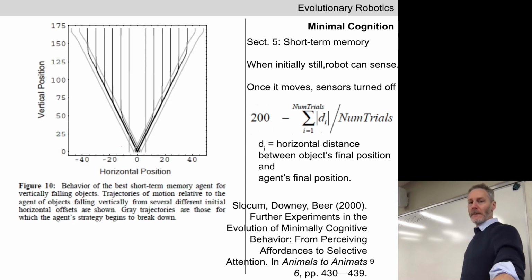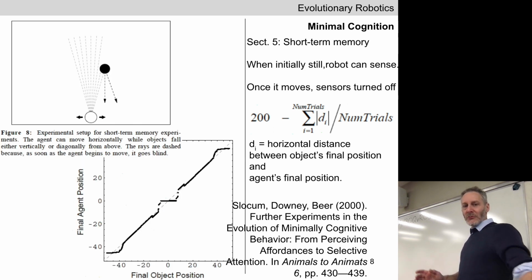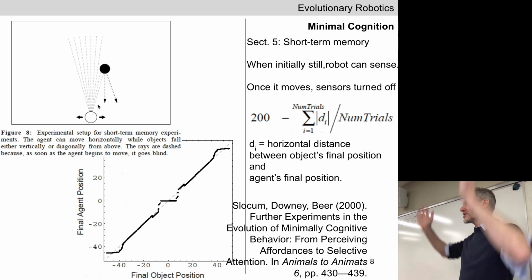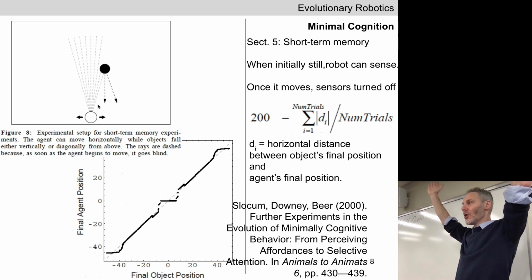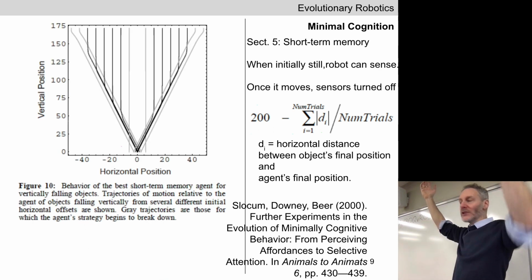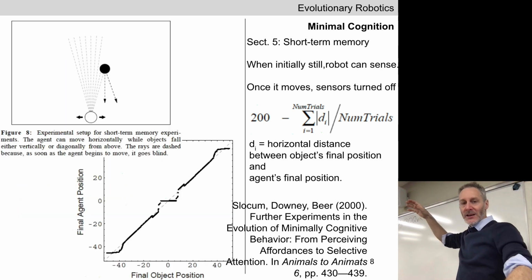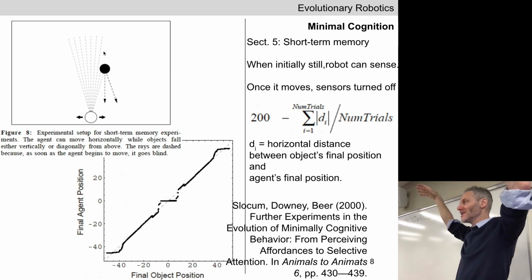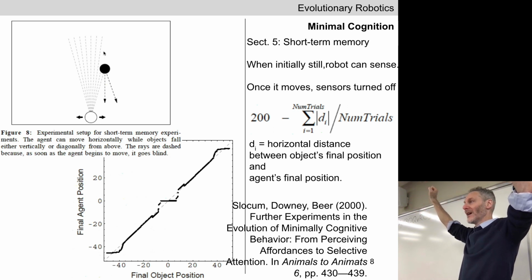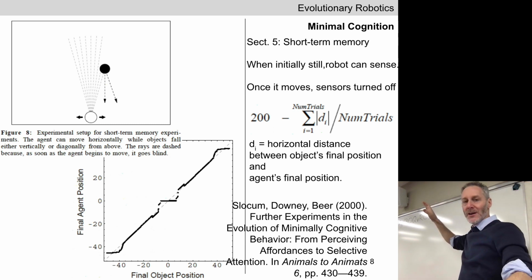Any other ideas? Why is it having a hard time with these edge cases? Is it out of bounds of the sensors, almost? Remember that these proximity sensors, before they turn off, are pointed up in a cone. So again, like a cat's whiskers, as the objects are falling straight down, the object is stroking the tips of these proximity sensors. The values are firing at non-zero values for a short period of time, but then the object passes underneath the cone of perception here.